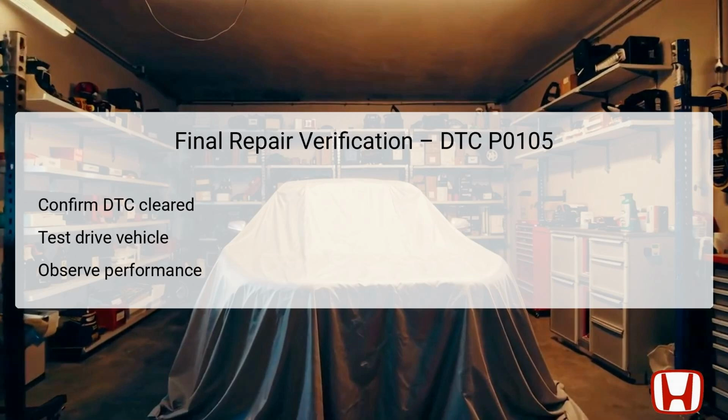During the test drive, observe the performance closely, particularly in areas where previous symptoms were prevalent, such as acceleration and idling. If any issues return or the DTC reappears, reevaluate the troubleshooting steps to identify any missed problems.